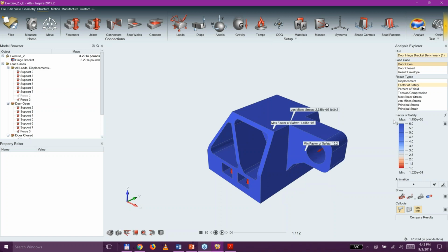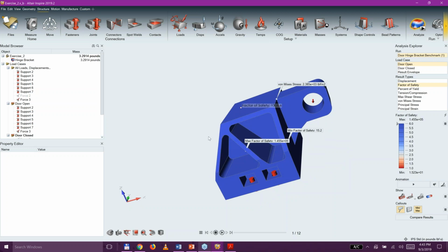That's devastating, especially when it comes to an aircraft part. Not because I want to make parts that aren't safe, but because this part is too safe. It means it's over-designed. And I put this on my aircraft, and I'm going to be flying around pounds of aluminum that are unnecessary. So I know now that even though there has been some light weighting applied to this, putting these little pockets in here, shaving these corners off, it's not enough.